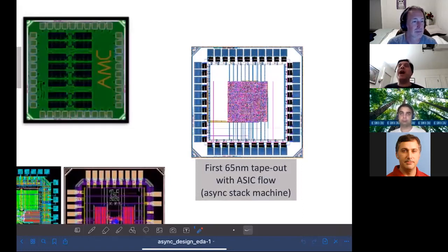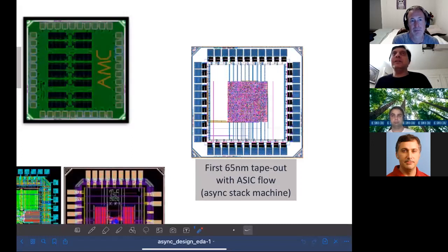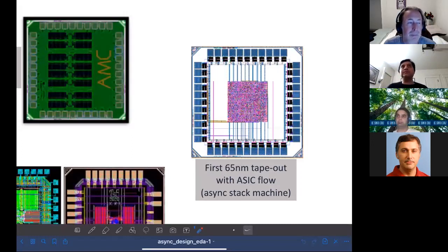It turns out that doing the cell wiring is a non-trivial exercise if anyone has ever tried to do it in any technology after like 0.35 micron. In an older technology, we have automated routers that can route cells up to about 65 nanometer. At 65, it starts becoming painful. The library doesn't do a good job, but older stuff we can do, that's not so difficult. But starting at 65, the rule that really, for those of you who are layout people, is the min area rule that starts getting really, really upsetting if you're trying to write a cell detail router.